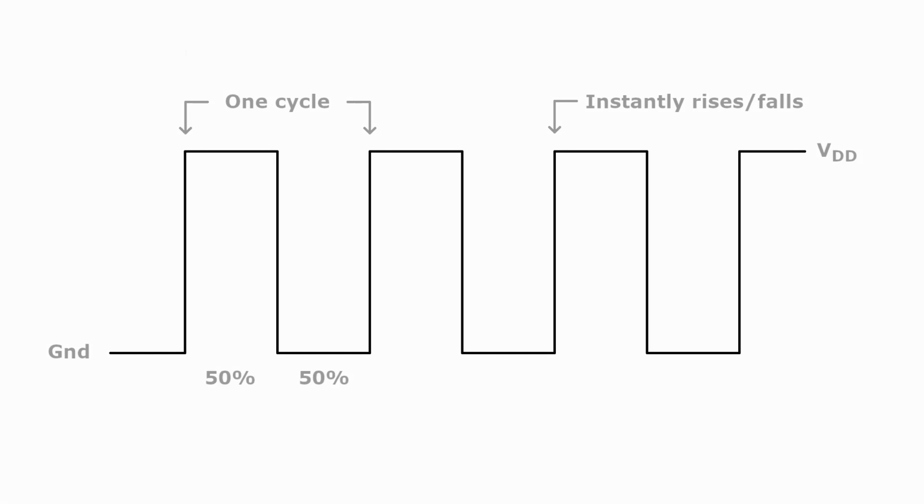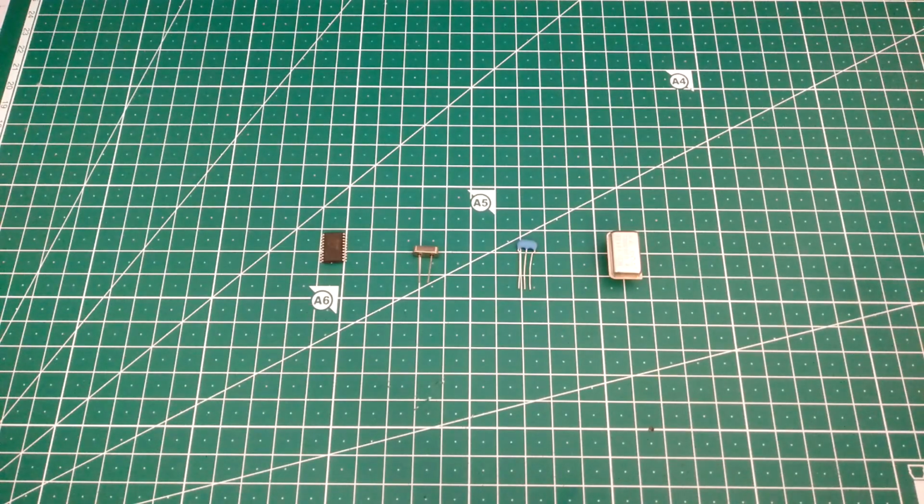It's a perfect square wave, about 50-50% duty cycle with the appropriate digital levels, so from the ground to the top power voltage, and with a fixed stable frequency. It does basically what the combination of the crystal and the load capacitors and the circuitry that's inside of a microcontroller would do, only that's all done in there. And the result is a clock.